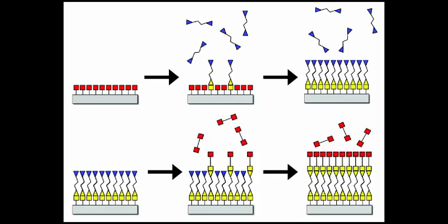Depending on the surface energy of the substrate or the already grown film, the film continues to grow as amorphous or silicon. The films can be amorphous, polycrystalline or single crystal depending on the deposition temperature also. In general, less than one monolayer of oxide can be formed. Let us see the formation of aluminum oxide over the substrate.